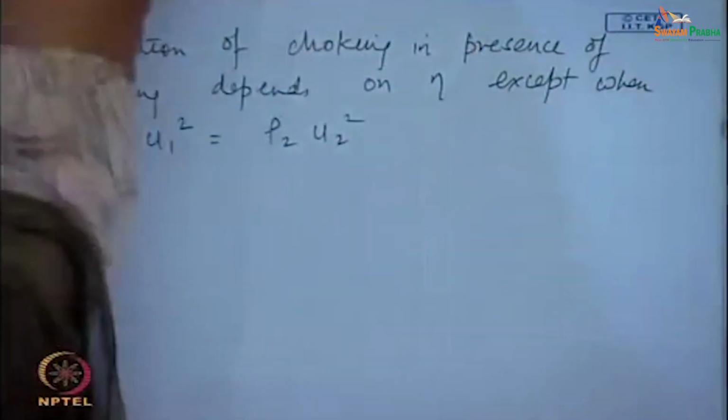So, now I would like to deal with another type of very simple situation. See, whenever we find that the two phases are accelerating through a nozzle, even for a single phase accelerating through a nozzle, we have a good amount of fluid in say any particular stationary tank, and then we have a nozzle connected to this. So, the fluid flows through the nozzle, a converging type of nozzle. Now, for that particular situation, which are going to be the dominating forces? Normally, the forces we have are gravitational forces, frictional forces and acceleration pressure gradient, isn't it?